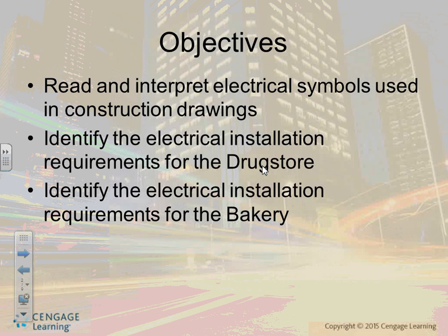And you can see the dimension. If you guys go to A5, please, we have the north and south elevation. Can you see how the upper one is the south elevation, no doors? There's an exterior light. Can you see two of them? They're sitting at the bottom of the exterior light, at the finished second floor. Can you see where it says finished second floor elevation 218.33?